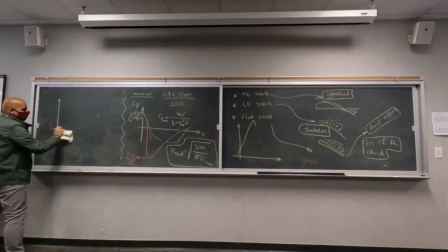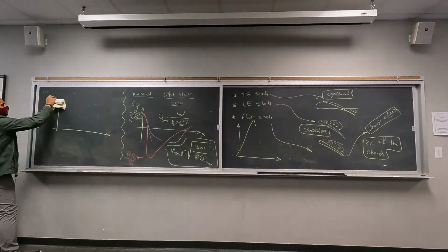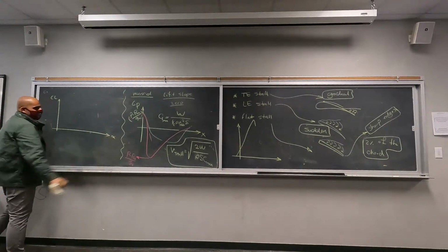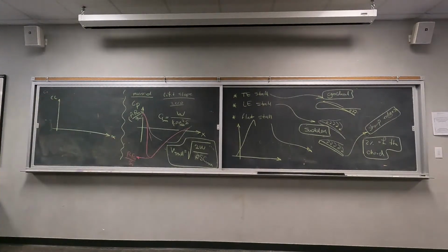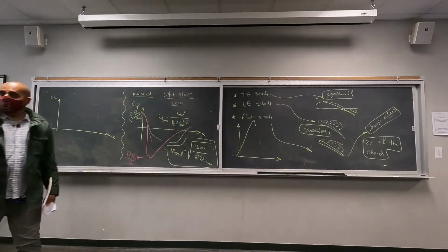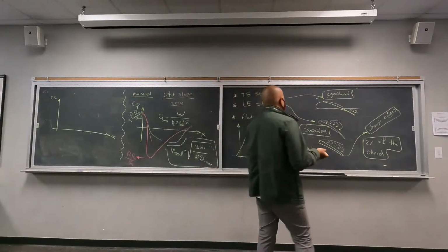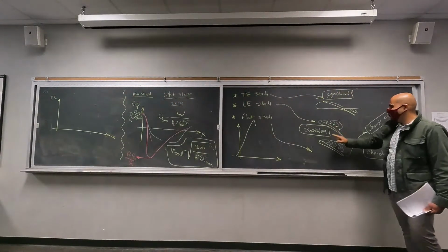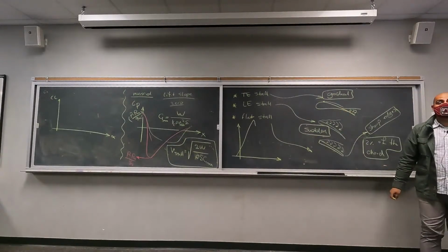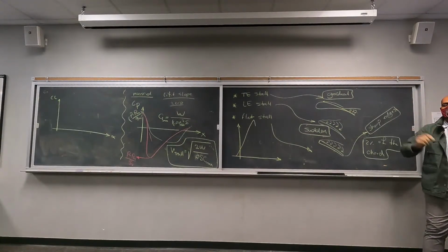Which one do you think will give you the highest lift coefficient? And the highest lift coefficient is going to be the lift coefficient during a stall, right? That's the maximum lift coefficient you are going to get. So whenever you hear the maximum lift coefficient, that's the lift coefficient during the stall. So essentially, I'm asking you which of these types of airfoils is going to give you the highest stalling lift coefficient.